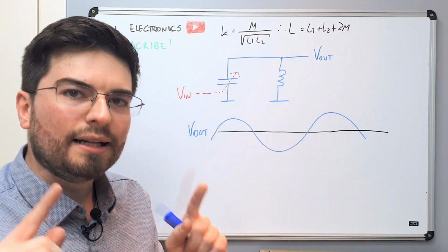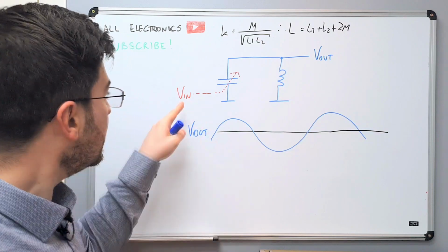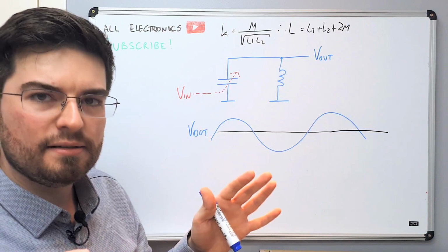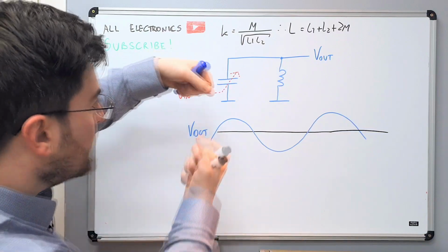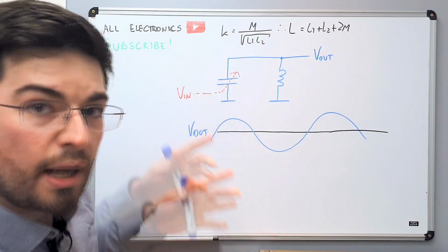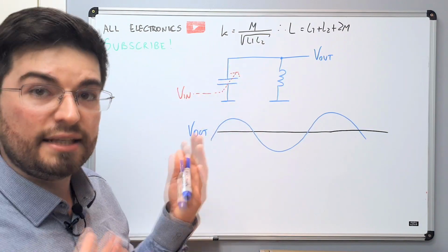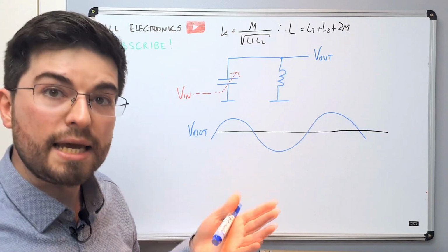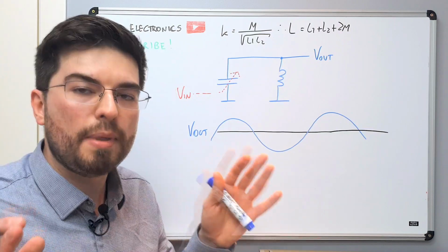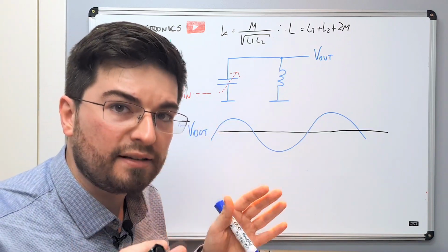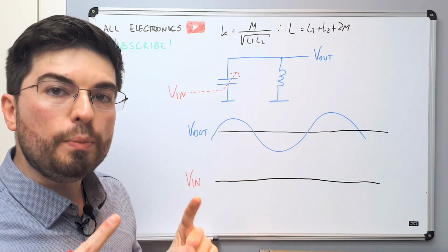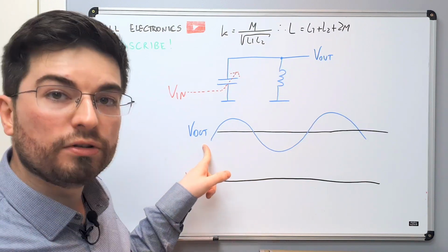Okay, now guys, let's imagine that we're going to apply an input signal that modulates the capacitance. Modulation of the capacitance is exactly equal to applying an external mechanical force pulling and pushing the two plates of the capacitor. We are changing the capacitance. A signal that modulates the capacitance could actually be a mechanical force changing the distance of the plates of the capacitor. Remember, we are trying to understand it from the perspective of energy. The input signal, the input force you're going to apply on the capacitor, will be at twice the frequency of oscillation of the tank.